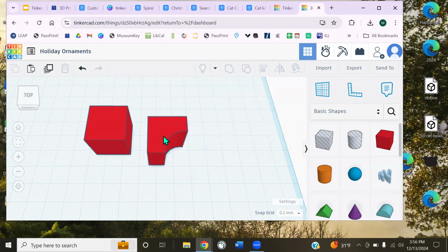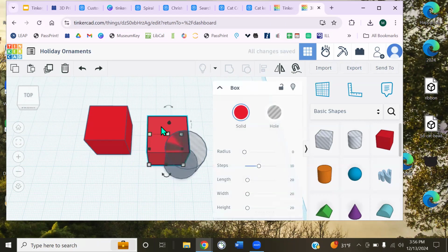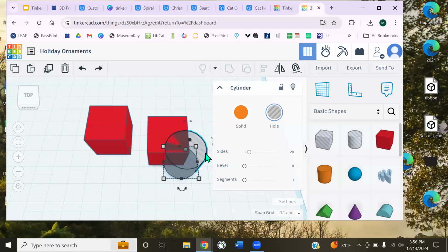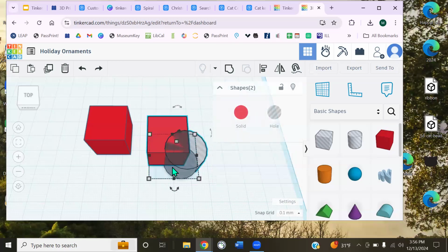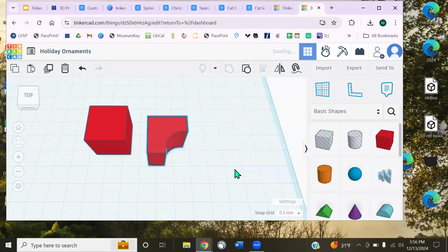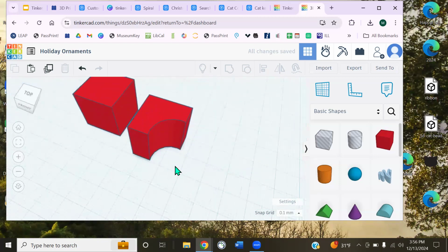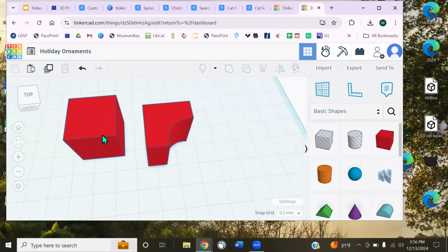And what it did is, I'm going to undo, it took the solid shape and left it solid, and it completely erased the hollow, the hole object. And if it was overlapping with any of the solid object, it's going to delete that stuff. I can use this as an erasing tool to subtract from my design. I have those two, and then we can obviously do the opposite with two solid objects.